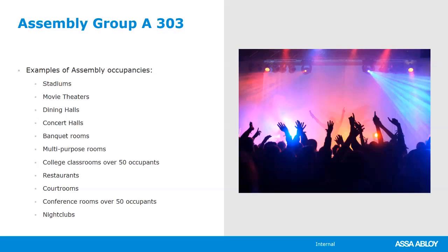Even though that wasn't true, people couldn't see what was happening. They could smell the pepper spray and they started pushing and shoving and going down the stairs. At the bottom of the stairs, that door swung in the wrong direction and people crushed each other to death trying to open the door, trying to get out. And it was a non-fire emergency. But imagine if that were an outswinging door with delayed egress. The same situation would have happened.